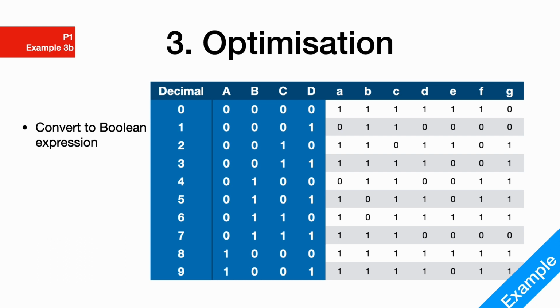After getting the sum of minterms, we will need to perform further simplification, for example, by using either K-map or binary identities. In this particular case, I've skipped ahead to show you the actual result of our optimization. But it is very important that you attempt at least to do it on your own first. Once you're done, let's move on to the next slide.